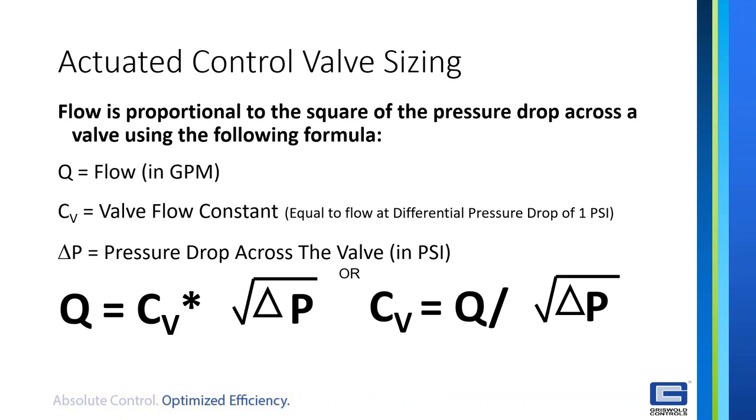But it also shows how the pressure drop and the CV are related. So if you have a given flow rate, if you select a high CV, you will have a low pressure drop. And that should make sense, because a high CV basically means a larger hole. Higher CV is a bigger opening, because if you remember our formula from last week, that CV is actually an area value. And so the CV is a value from our test lab, but basically a bigger CV means a bigger hole, and so the bigger the opening, the less the pressure drop is.